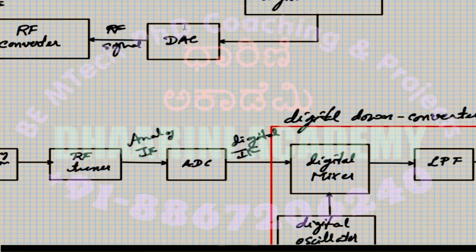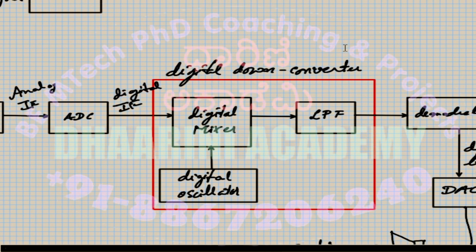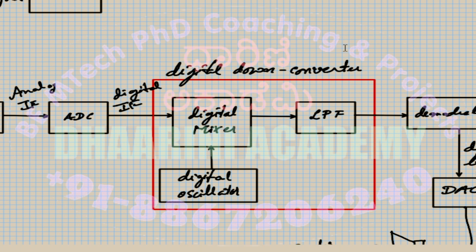But here I should do the reverse. It is in the high frequency, and I have to convert this into low. So you do a reverse process called decimation. There you do the interpolation; here you are supposed to do the reverse of that process, called decimation.